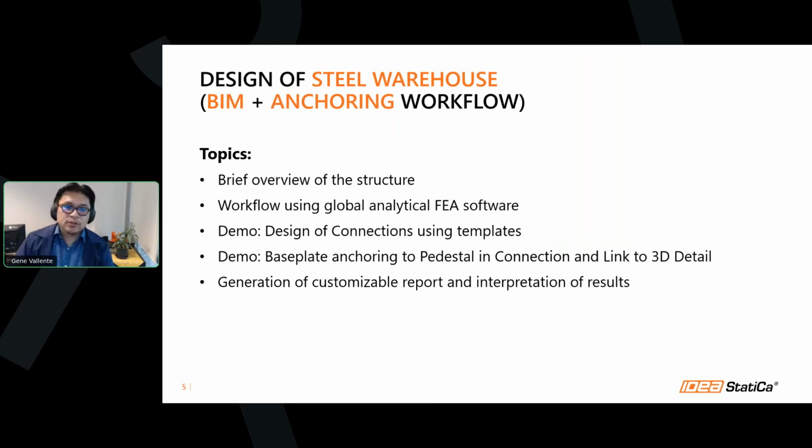We can make use of that as well. And of course, I will also demonstrate the baseplate anchoring to pedestal using detailed 3D from the connection application, and how reinforcement in concrete can be considered to produce a more optimized design. And lastly, I will also discuss the generation of customizable report, as well as interpretation of the results.